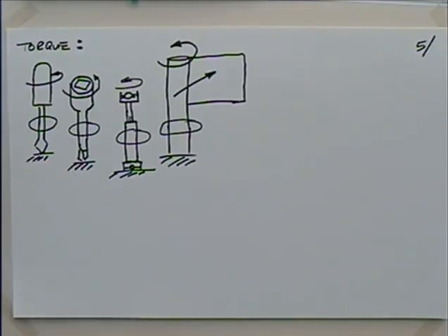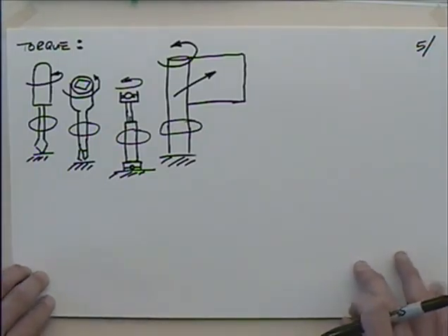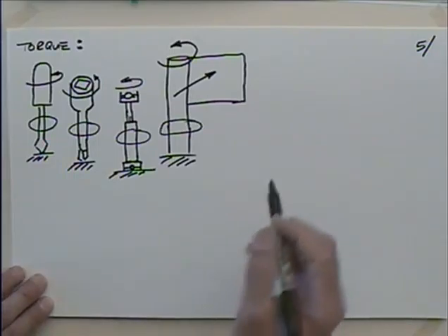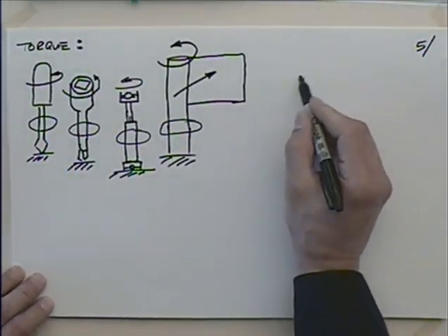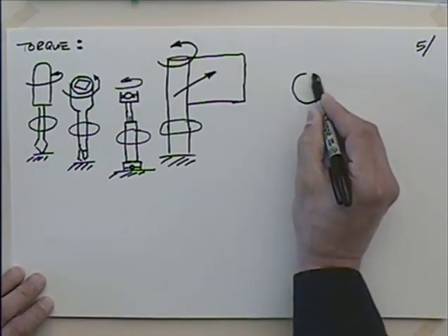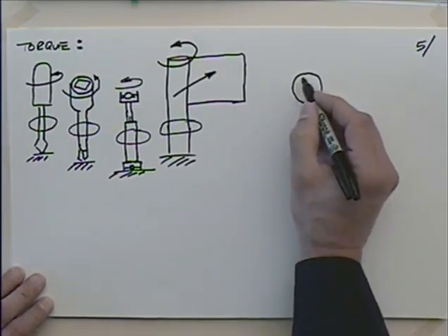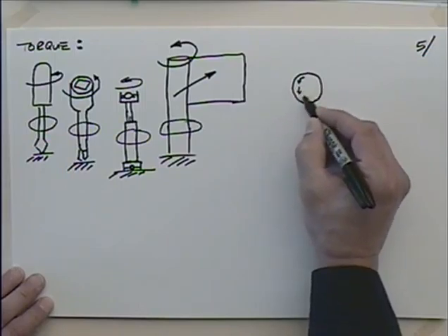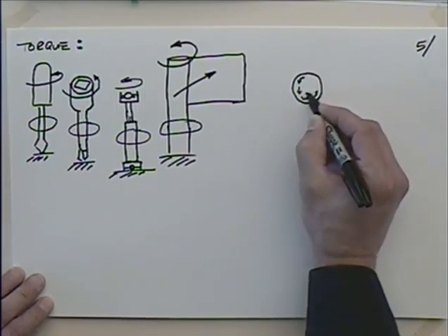I'm going to start talking about this from a standpoint of having a solid shaft, but eventually we'll see the virtues of having a hollow shaft and go from there. So in general, if we look at the cross-section of this, whether this is the cross-section of a screwdriver or the cross-section of a drive shaft, that shear stress would be carried across the entire surface like this.